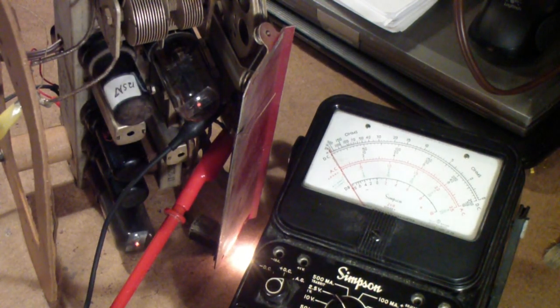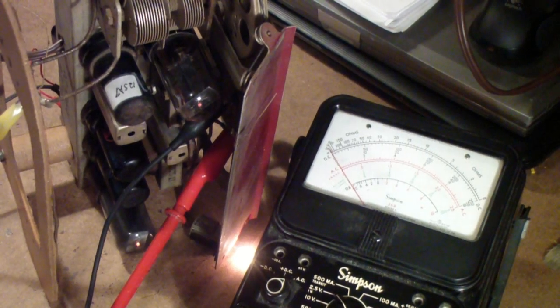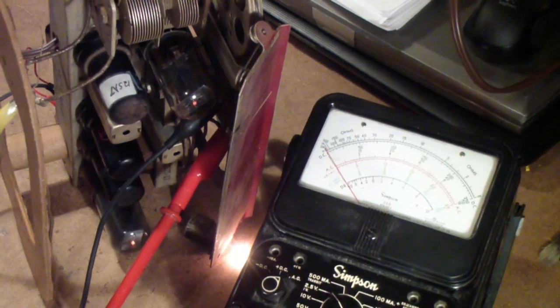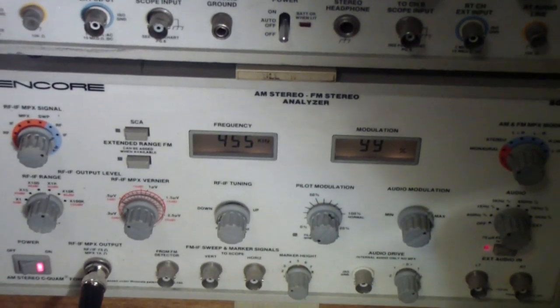So, what is really going on here? Well, I suspect most of you already know. What we are doing is tuning the intermediate frequency stages. That is, those 2 transformers that couple from the converter through the IF stage to the detector. So we're maximizing the gain of this receiver at one frequency. And the frequency that we are using is 455 kilohertz.